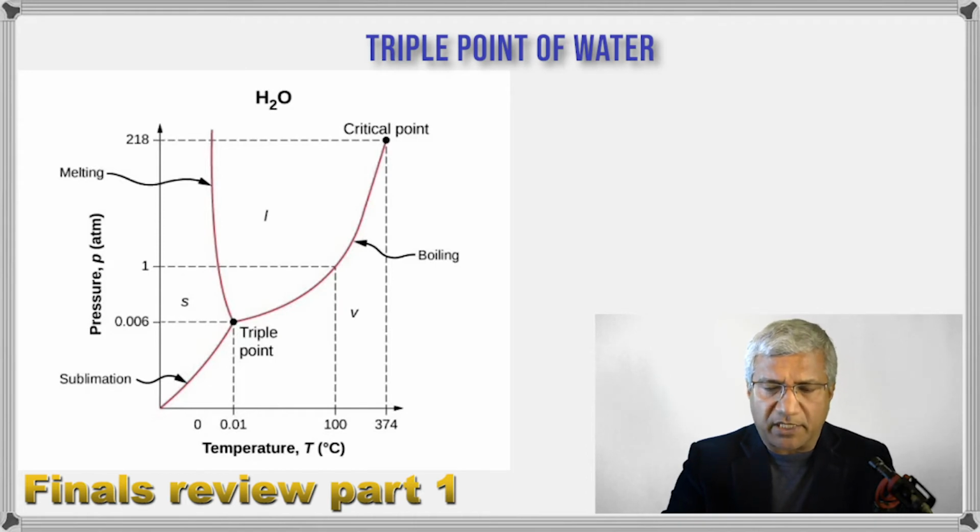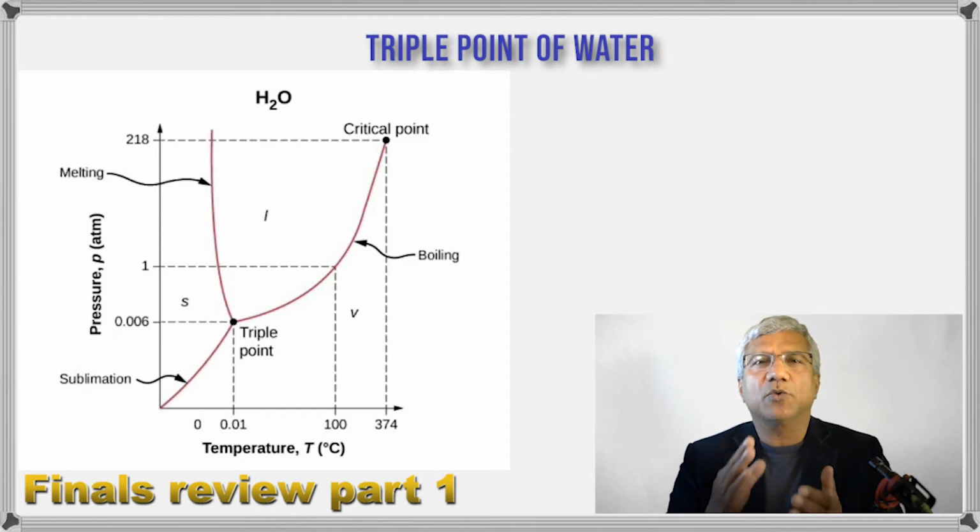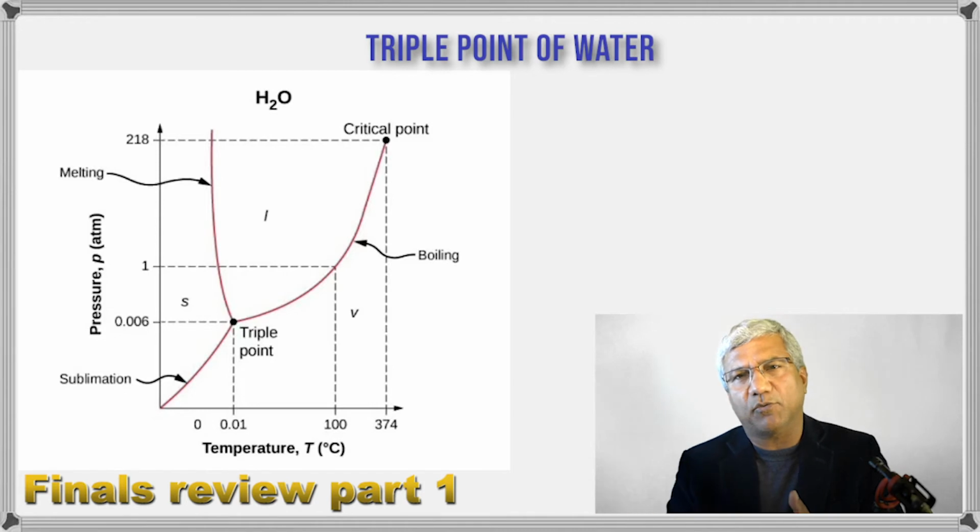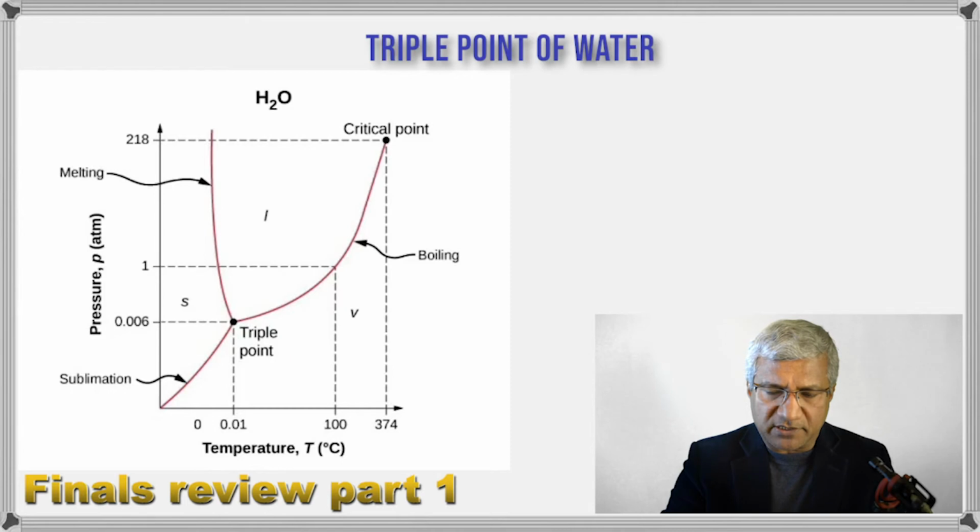So again, at every point on the left of this graph, it's water, but on the right side, it's a vapor or steam. And then you have the sublimation curve. You know what sublimation is? Where the solid directly changes into vapor without passing through the liquid phase. So that's a sublimation curve. And then at every point, here it's a solid, here it's a vapor. So you see the meaning of triple point now. All these three curves meet here or intersect there.